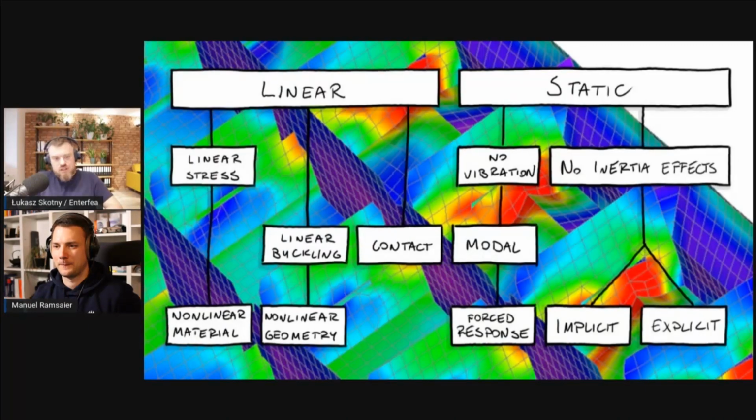Yeah. And if something could vibrate, it could potentially fail due to vibration, be it fatigue or resonance, it could be both in some sense, but let's leave this aside. The idea is that you have to analyze it, so you want to know if your thing will shake. It's something akin to stability, really: if you're not expecting it, it will catch you off guard. You can do your linear, static, or even nonlinear analysis and be a happy camper. You just don't know it, right?